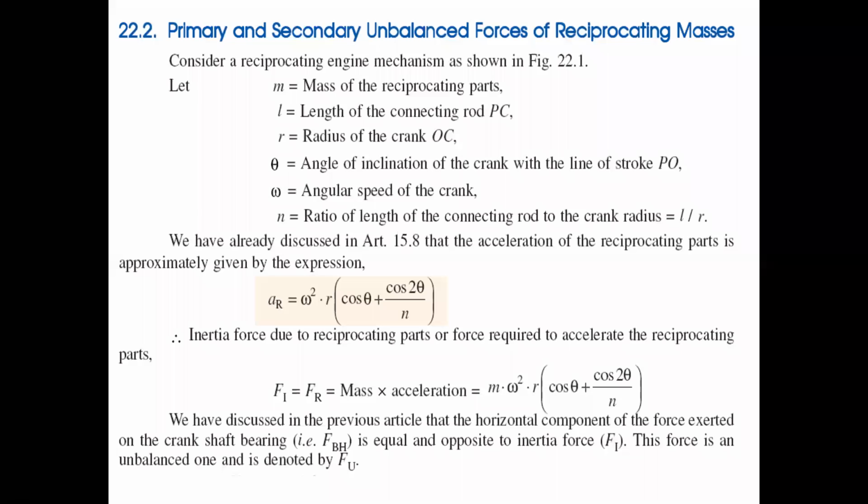And to recall the velocity, which we have already done, the velocity of the piston is omega r sin theta plus sin 2 theta by 2n. So that is the velocity of the piston, and this is the acceleration of the piston.